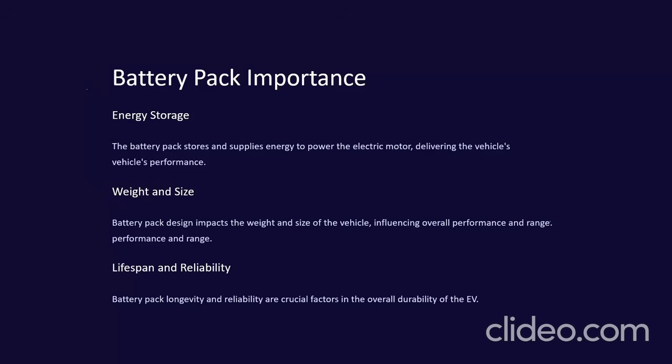Lithium ion battery is more popular in the electric vehicle industry, and each different type of lithium ion chemistry has a different temperature range in which, if you operate the battery, you will get the maximum efficiency out of it. You should remember the temperature range in which the temperature of the pack will vary in the particular application where we are going to use that battery.